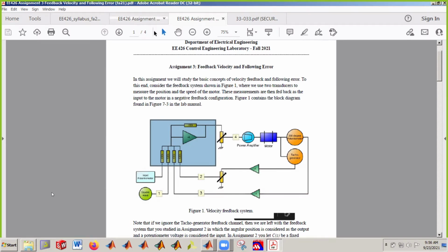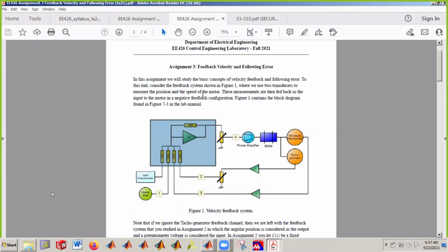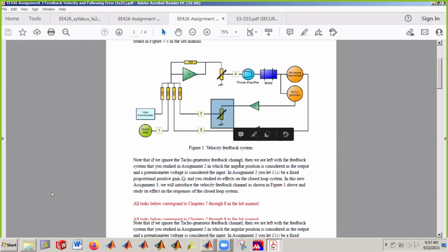In other words, this is a summing junction. We call it a summing junction even though you have a minus here, because these things work on the same principle. Two signals come in here. Now, because we have an additional signal that we want to feed back, we need to extend the summing junction. This is the way you would see it in the lab, using this op-amp and several input resistors. But pay no attention to this for now. KV will be right here. So you should be making a note as to what KV is doing for us here.